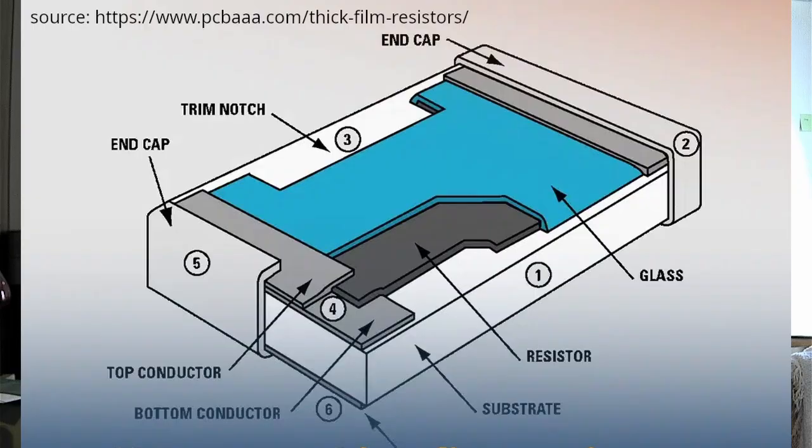The first one I'll talk about is thick film resistors. These you want to consider your everyday normal resistor. These are going to be really cheap. We're talking less than pennies for most of them. The way these are built is you start with a ceramic substrate and then you put a conductive ceramic layer on top of that. That is the thick film, and you fire it. Thick film, it's cheap, it's common. Consider this your default choice for most applications.